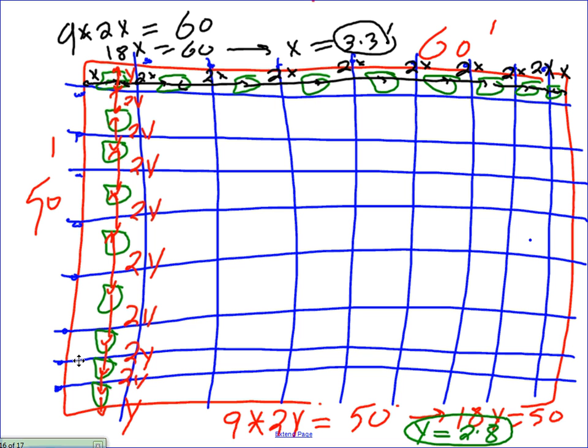I would like you guys to draw the same thing tomorrow. Is that hard? Dustin, does it make sense? No? So 3.3 is the width of each section. The 3.3 is the center of the fixture. From here, let me just go with the black here. The 3.3 is from here, the center of the fixture, to this side. This area is 3.3. The 2.8 is from this side to the wall. The x and the y are to the center of the fixture.